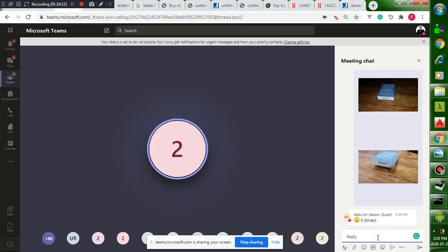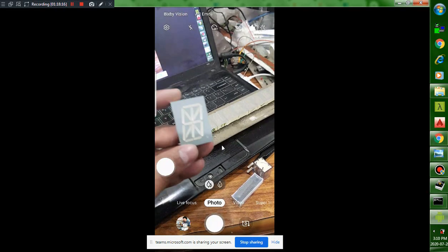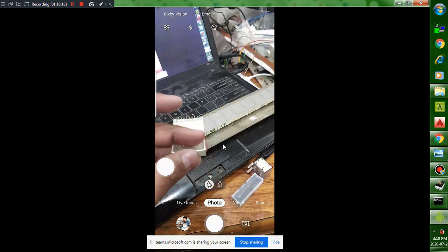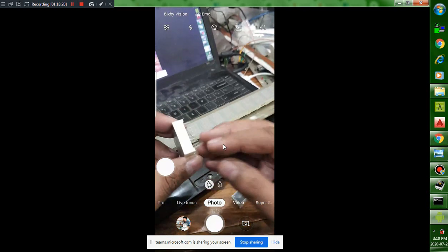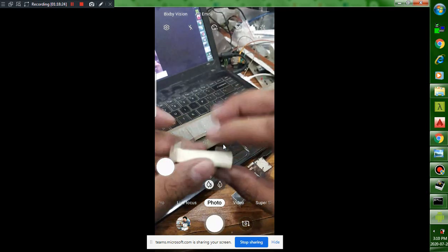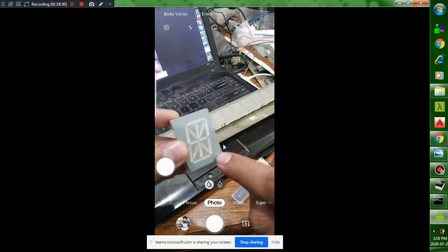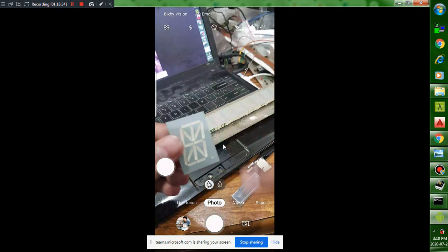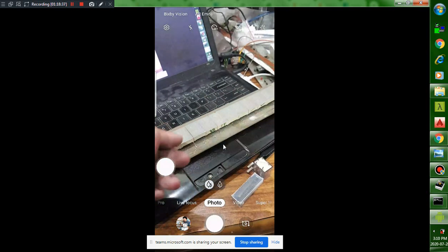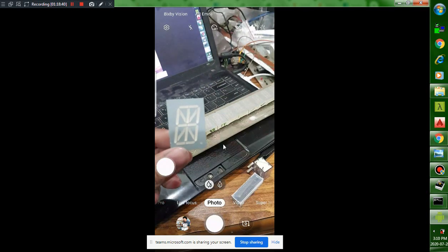since I have not yet given the data sheet of this 7 segment, and also the alphanumeric, which I am holding in my hand at present. This is the same alphanumeric. You can see how many pins there are: 1 2 3 4 5 6 7 8 9 10. So there are 20 pins. And how many segments are there? There are 16 segments. So 16 plus 1 dot is 17, and then the remaining 3 will be the power entry points or the common anode points. Please remember, this is common anode, the one which I am holding at present.